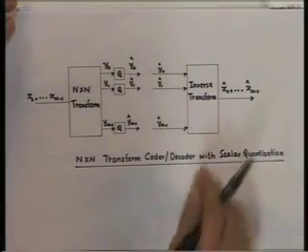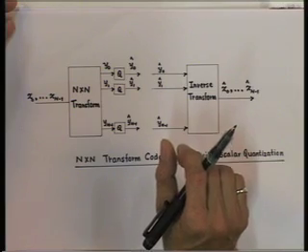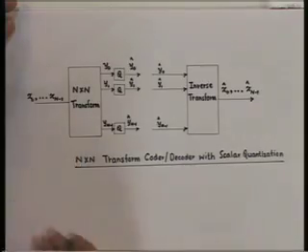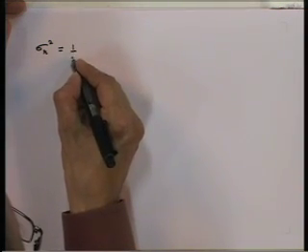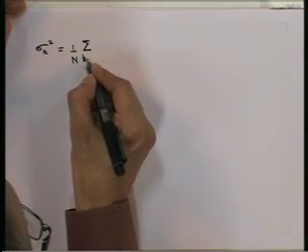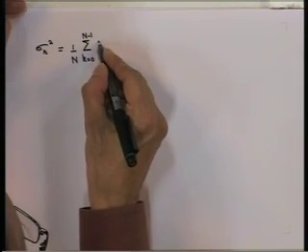Now, another question that arises using this strategy is, what is the mean squared reconstruction error? That means, error between the reconstructed sequence and the original sequence. So, this can be written as: mean squared reconstruction error is equal to 1 by n summation of k equal to 0 to n minus 1 expectation of the squared error.